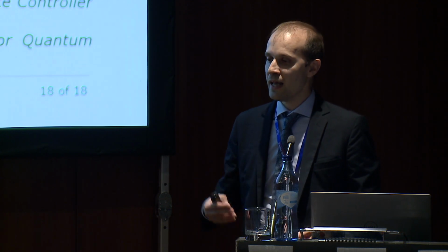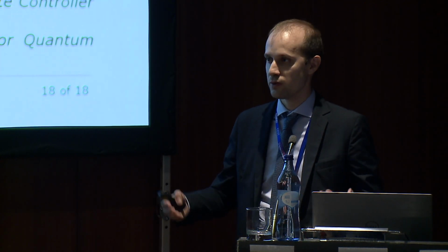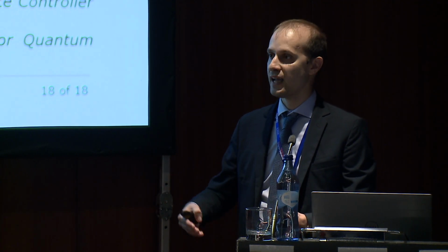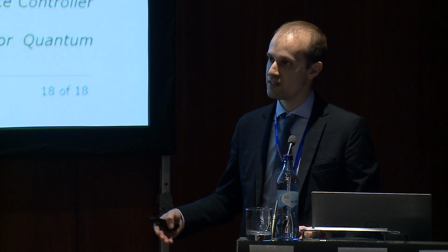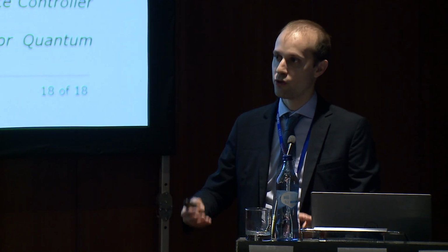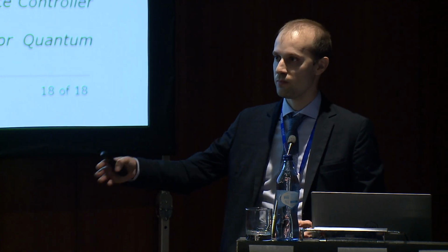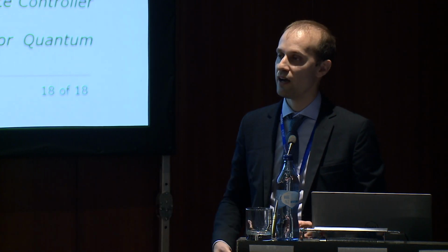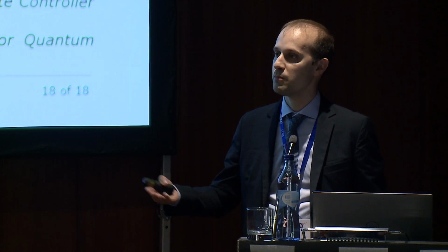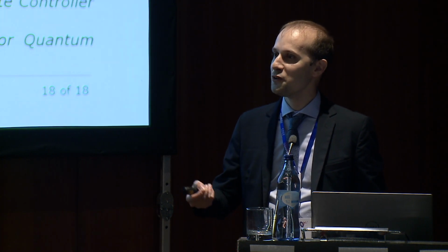Mismatch gets worse. And now I think in the community, we are evolving on that front. So there are, especially for the organizations that can afford that, efforts in fabricating test sites with individual devices during the characterization and moving towards a more industrial set of cryogenic models. First developed in-house, from university research groups or industrial efforts. And I think eventually we'll get there where there will be PDK models provided by foundries directly.